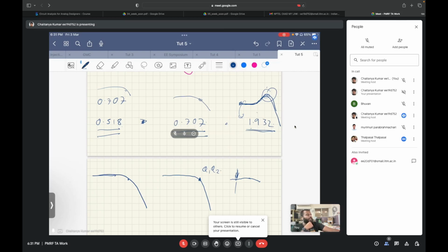So if you multiply this, you will end up with 1, and overall you have 0.707. So you will see always in this case, for example, if you design a first order biquad, sorry, a second order biquad, you will see a quality factor of 0.707 itself. Okay, 1 by root 2, correct?